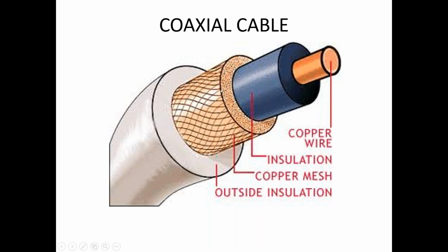There is an outer conductor called the shield. In between, you need something to insulate it, and that is an insulator. But we're also going to learn that this is called a dielectric material. It does not conduct electricity, but it does allow for charged fields, positives and negatives. And then, of course, there's a jacket protecting it.